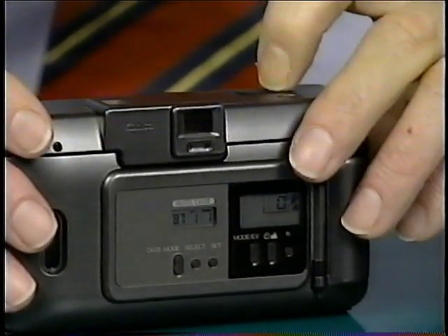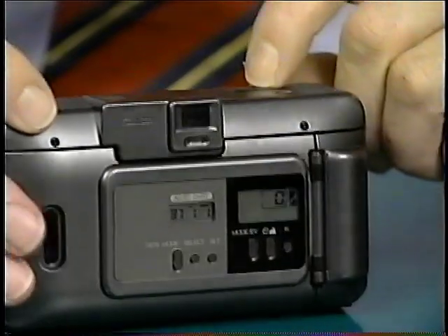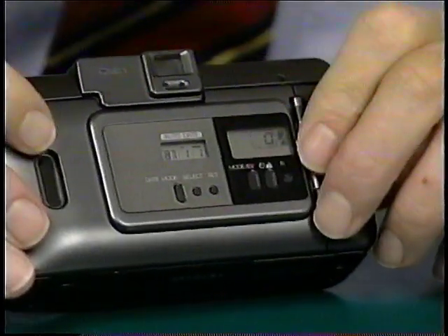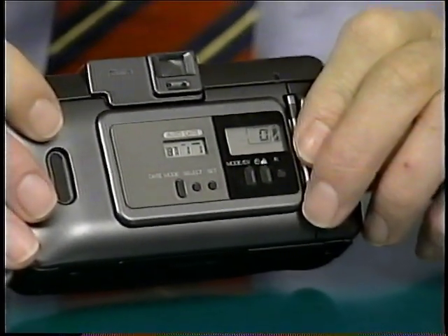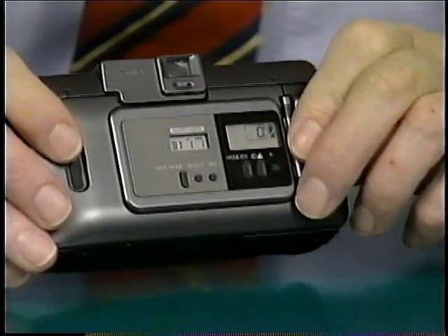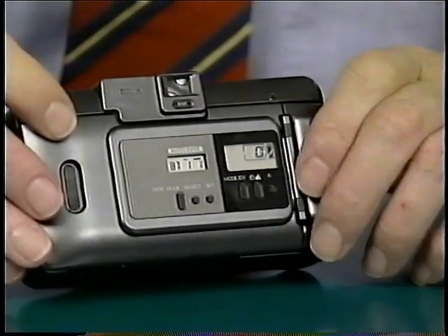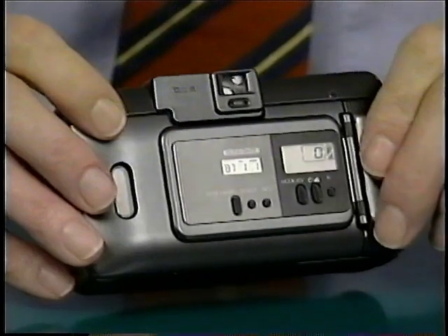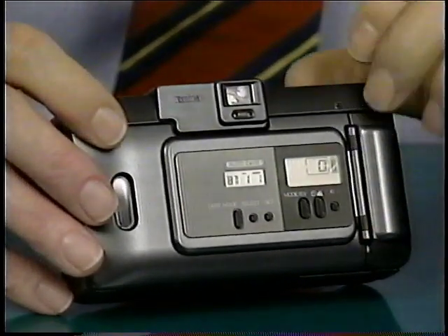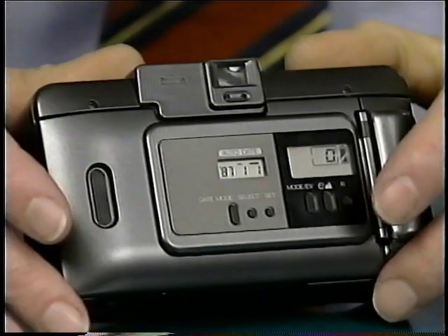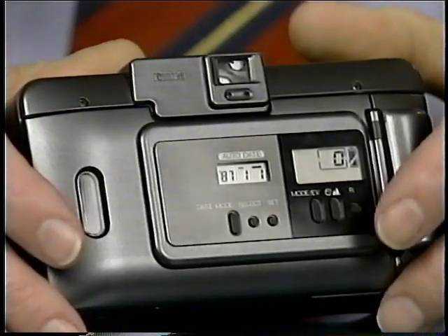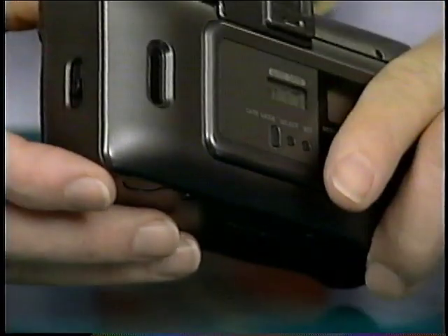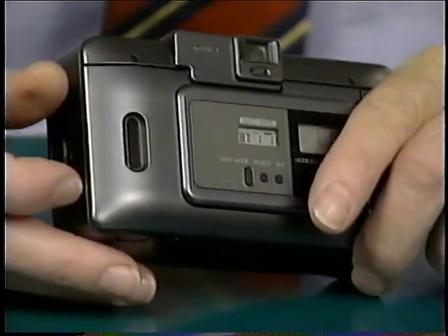There are a few cameras which do not go through the loading process until the release button is pressed the first time. But at any rate, all cameras of this type, the newer modern electronic cameras, will go through an auto load process. We've already seen the APS camera. It does the same thing. It sequences the film and then loads up to frame number 1. If they don't do that, or if you hear any unusual noise in the film motor when that's happening, you can suspect there may be sand in the camera, perhaps a broken gear, or bad switches which are not detecting that the film door is closed.